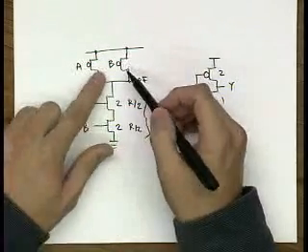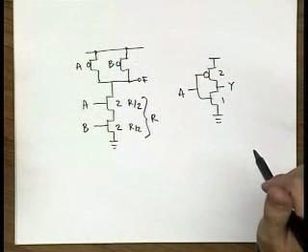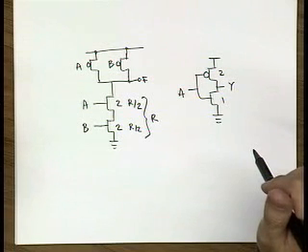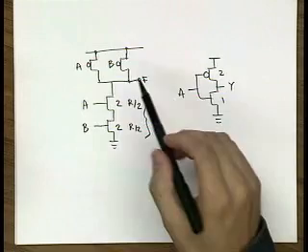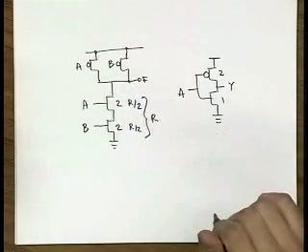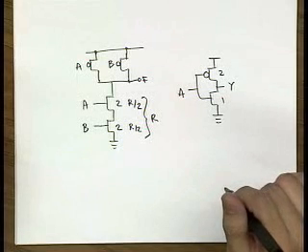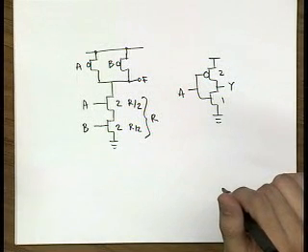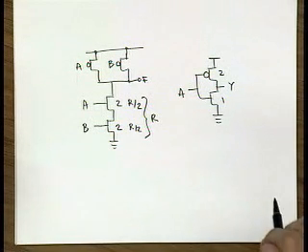How about the PMOS pull-up? What do you need to do to make the same pull-up as the inverter? What happens in the worst case? Only one transistor pulls up, right? Forget about the intrinsic capacitance and all other stuff. First order. Why 1/2? But what's the worst case?